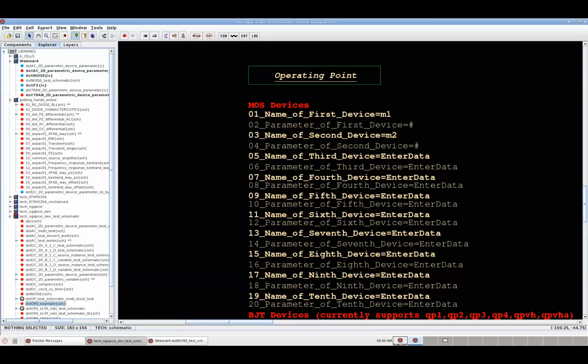Does it matter? Will it have anything to do with the layout tool? Does it have anything to do with global variables, or is it just names? Should we name our supply and ground in a special way, because this will have cells within cells? Will it propagate the way it should, or will it cause problems? Will it coincide the way it should when doing the parasitic extraction?